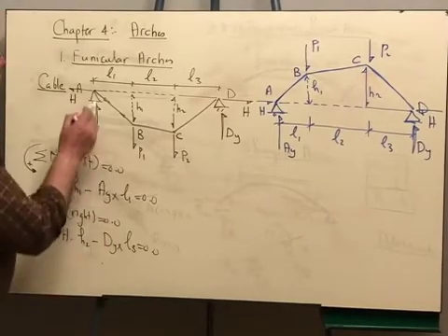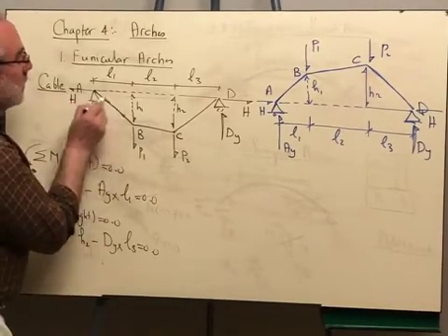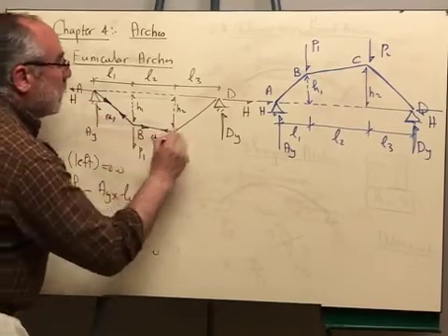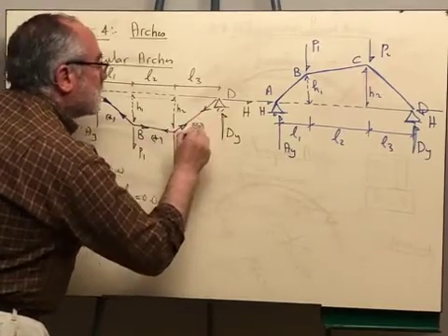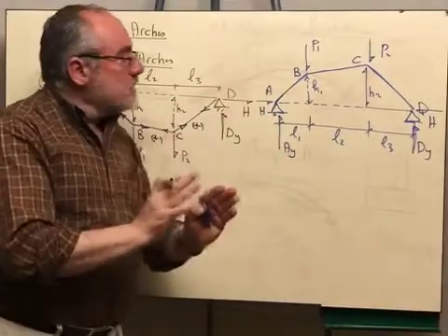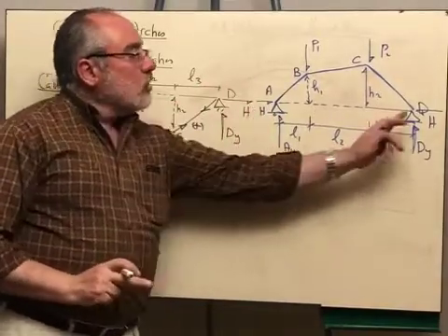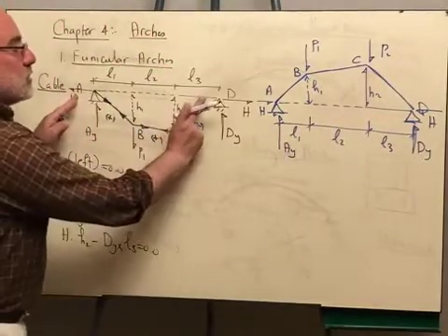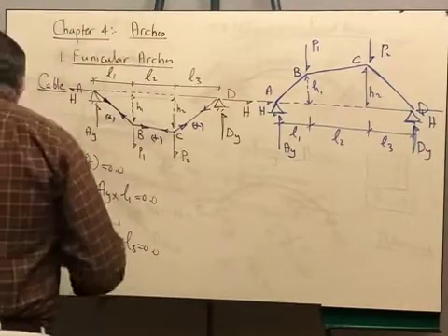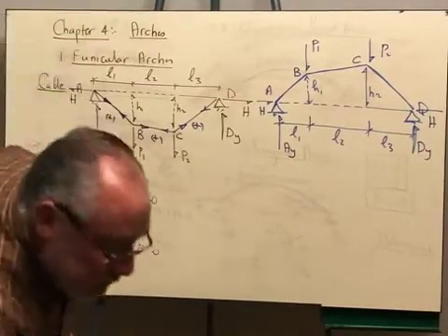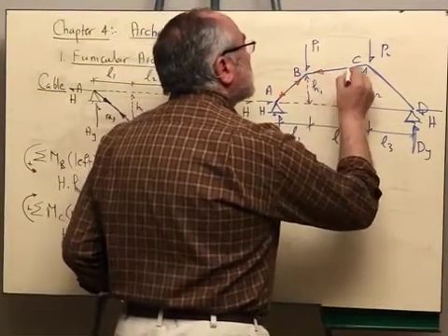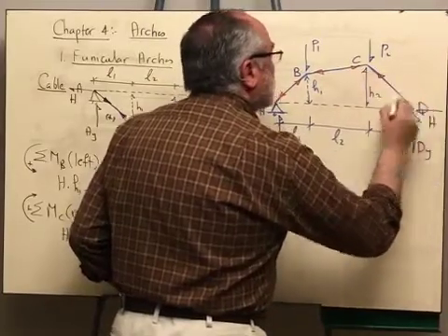So now, in this situation, when it was a cable, it was supporting tension force. The force is getting out of the joint. But when we reversed the problem and we took the same geometry and the same loads exactly, the direction of the horizontal reaction is reversed. This horizontal reaction is outward, this horizontal reaction is inward. And what will happen? The member will develop normal force compression. So the internal force is towards the joint.